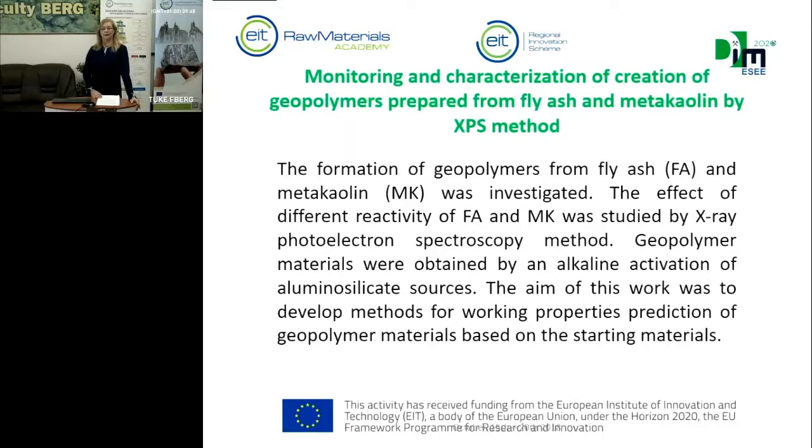Another use of fly ash was the formation of geopolymers from fly ash and from metakaolin. We tried to investigate the differences between fly ash and metakaolin. The aim of this work was to develop methods for predicting the working properties of geopolymer materials based on the starting materials.